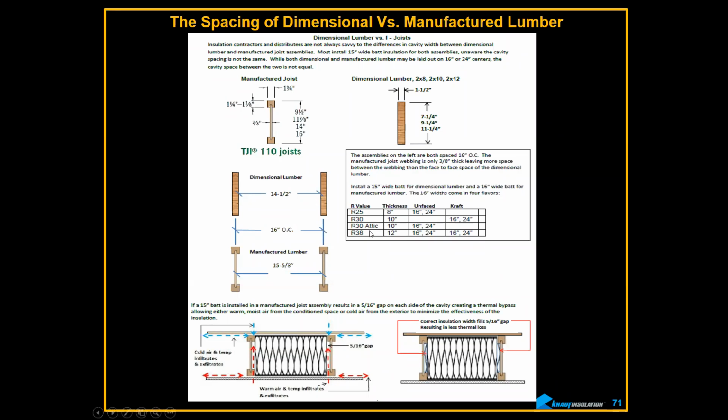Anyway, you have to order the right material for the right length, and part of the problem is that the manufacturers don't tell you this, because all of the manufacturers put these numbers and this data in metal framing. So if you're not looking at metal framing, you would never know that these bats have to fit in here in order for them to work. So manufacturers are pretty guilty.